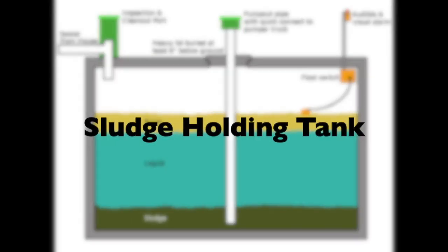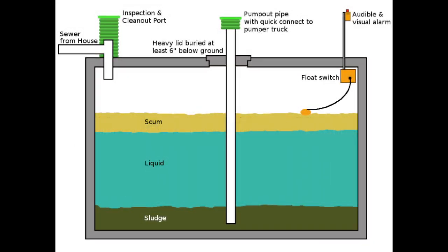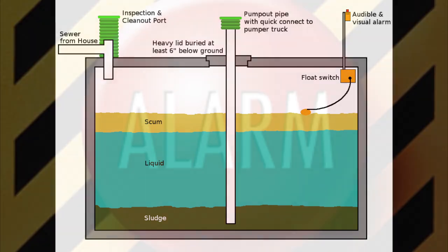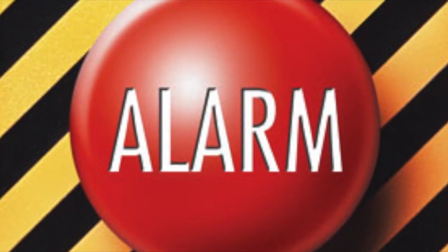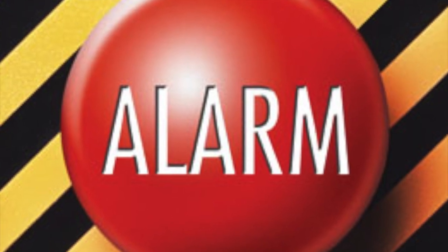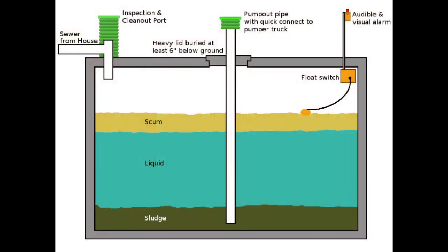Sludge holding tanks provide storage and blending for the thickened, activated sludge, primary sludge, imported sludge, and scum before further processing. Most holding tanks are equipped with alarms that will sound when they are nearly full and will require pumping shortly thereafter. Level of sludge is the control variable.